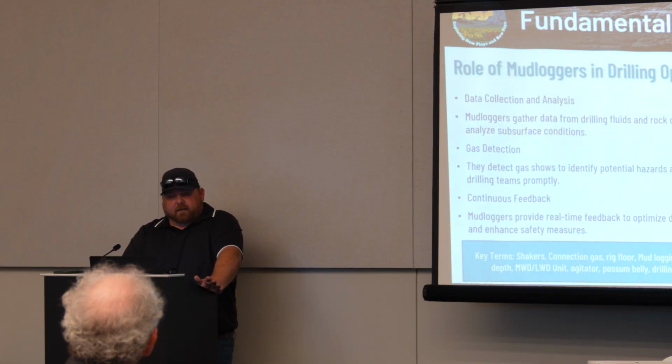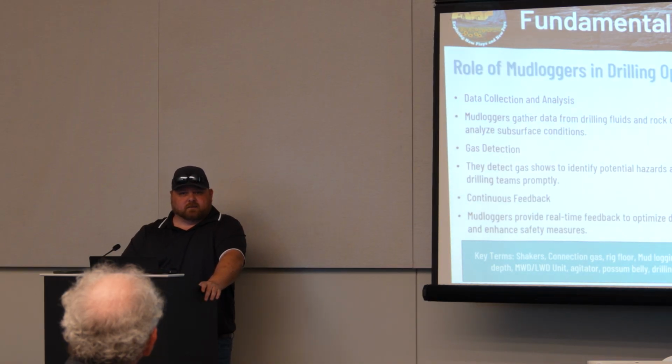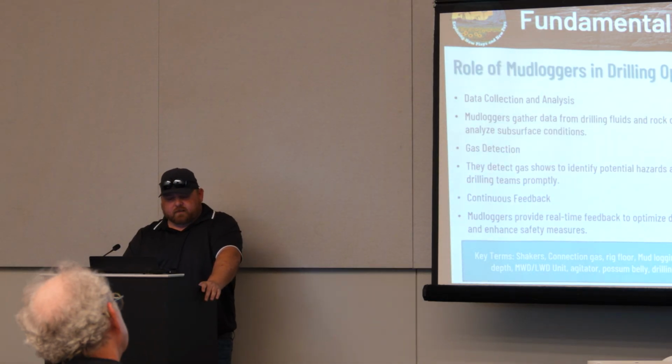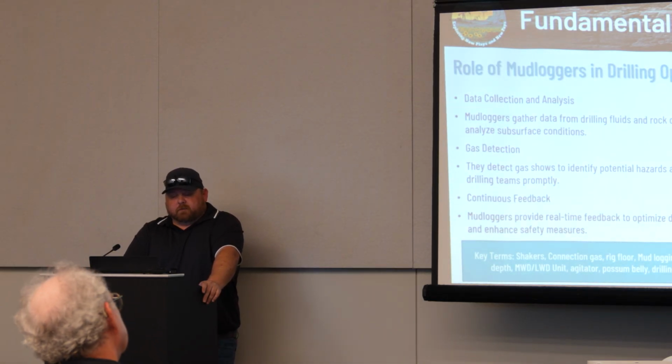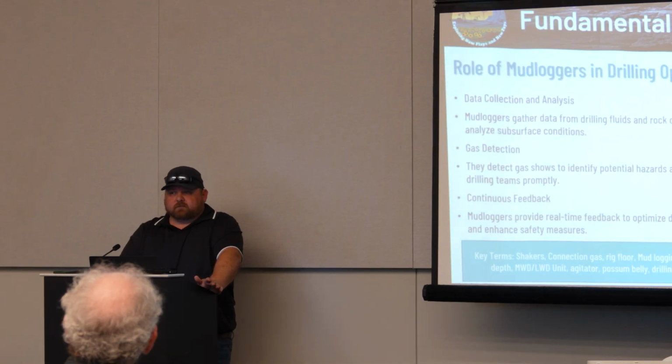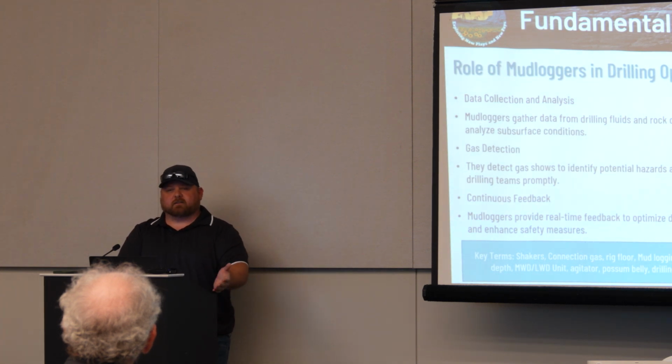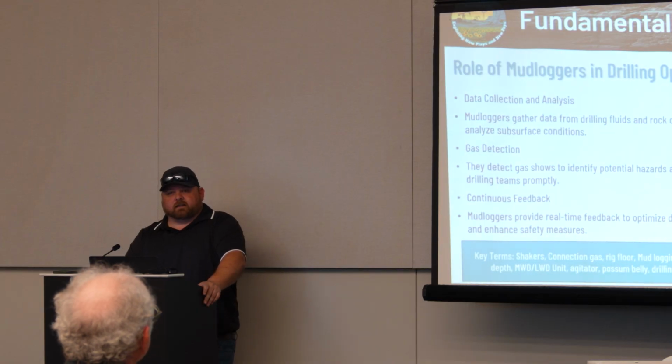Along with that, gathering the data from the drilling fluids, mud weights, viscosities, low gravity solids, all that goes into account for our gas systems and detection of the gas readings. Also helps identifying the hazards. If we see a drop in mud weight with a high gas spike, we're getting gas cut in drilling fluids, and that's going to cause an instability in the wellbore. Hydrostatic pressure of the wellbore is going to drop in that case.